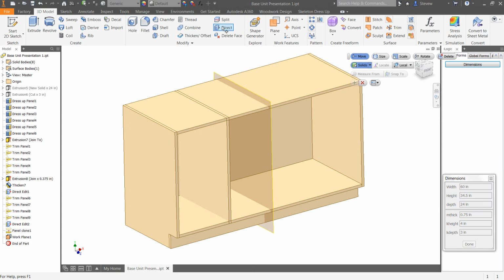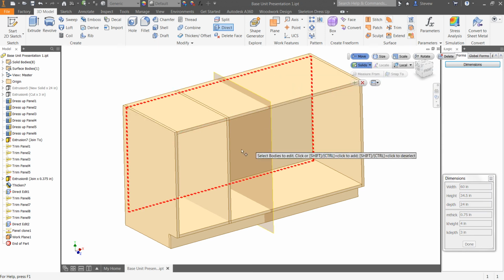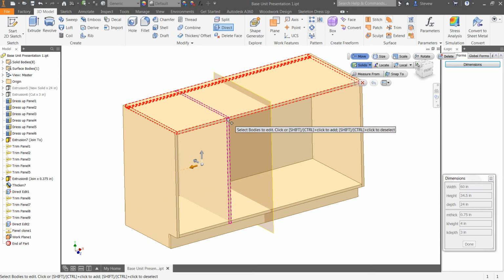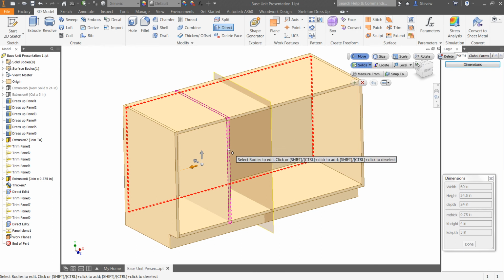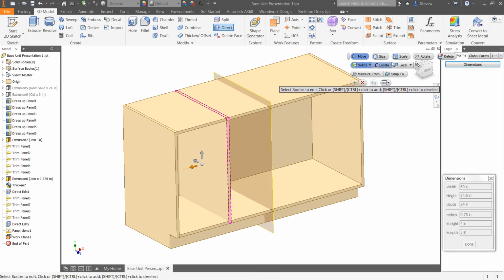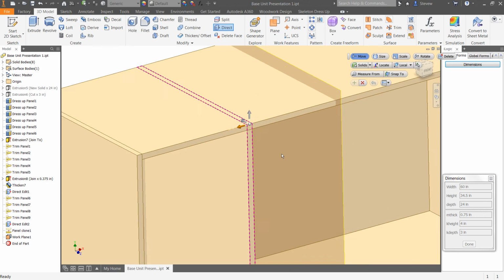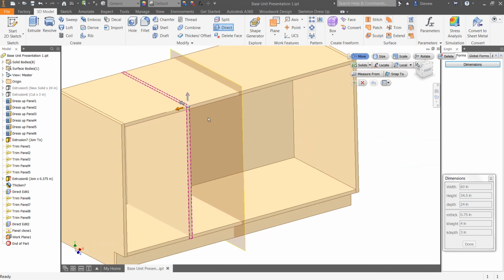And then using direct edit again, I'm going to move this particular unit, but I have to move it from the center of this clone to this actual center of this work plane. So that's where we say locate. And I'm going to locate the center, which is what I just did. It found it automatically.